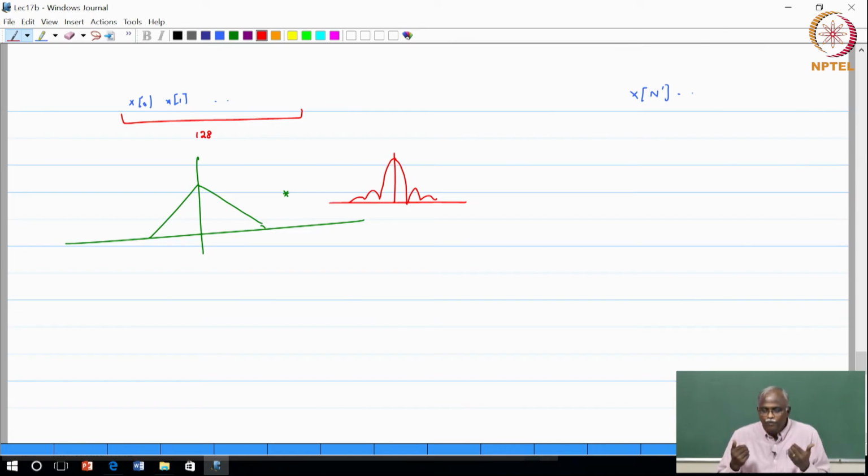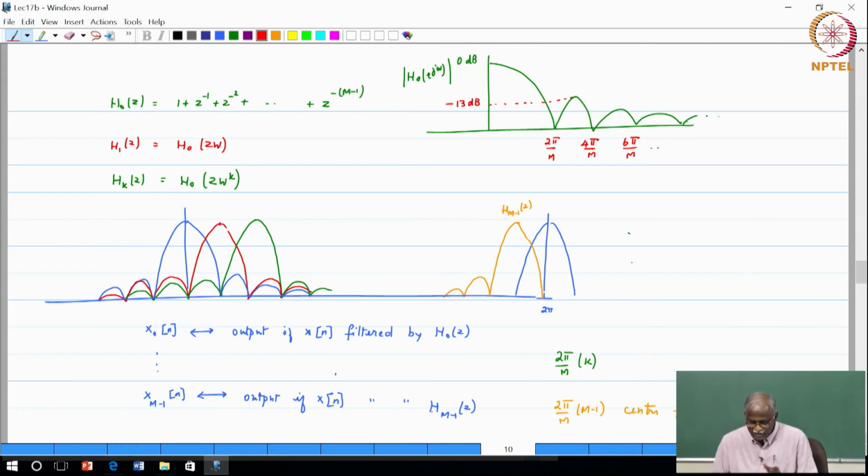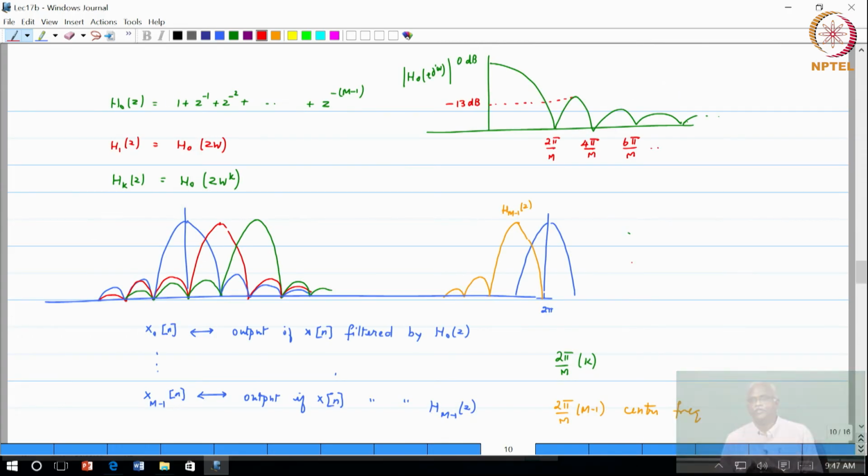So, the way I want to look at it is from a filtering point of view, instead of doing a rectangular window followed by a DFT, then sliding my data, doing another DFT, and going through the process of obtaining my spectral estimation. What we are saying is, hey, by the way, this is the same as passing it through a filter bank. So, you can take your data, not need to window it, just pass it through a rectangular window based filter bank. This type of filter bank is exactly what your DFT is also effectively doing. Okay.